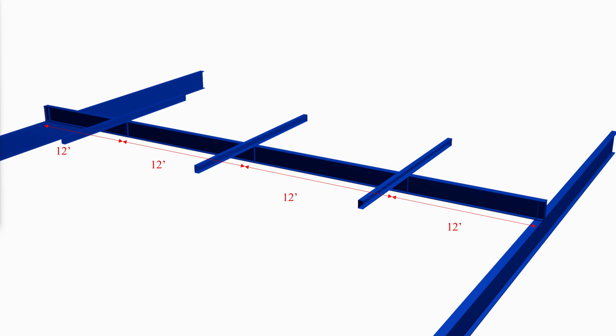Let us start by defining our example problem, where we have a 48-foot long plate girder, and lateral beams rest on the girder at 12 feet offset of each other and from the end supports of the girder. These create concentrated combined ultimate loads of 60 kips. This also creates a lateral support that will prevent rotation of the top flange of the girder at these points. The end supports are treated as simply supported.